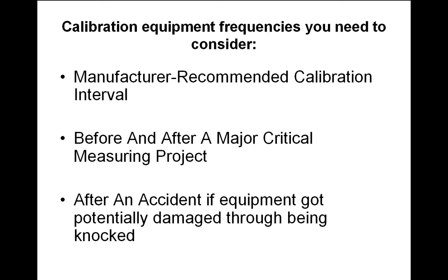Just to go back on this, if you get a meter, like a DMM, I wouldn't even know how to calibrate it. With the AVO or analog meters, there are little screws inside and little potentiometers where you can actually do some calibration. When you do a resistance measurement with an analog meter, you have to calibrate it anyway. You put both leads together, and then you've got a little potentiometer, and you tune it in for 0.